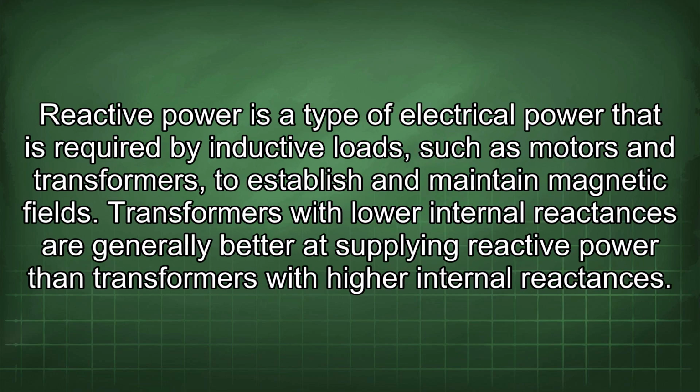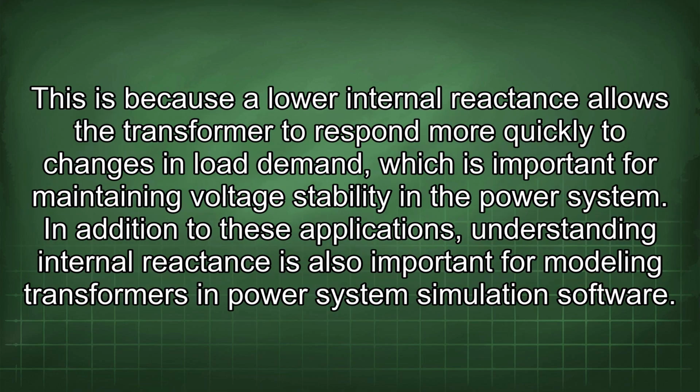Reactive power is a type of electrical power that is required by inductive loads, such as motors and transformers, to establish and maintain magnetic fields. Transformers with lower internal reactances are generally better at supplying reactive power than transformers with higher internal reactances. This is because a lower internal reactance allows the transformer to respond more quickly to changes in load demand, which is important for maintaining voltage stability in the power system.